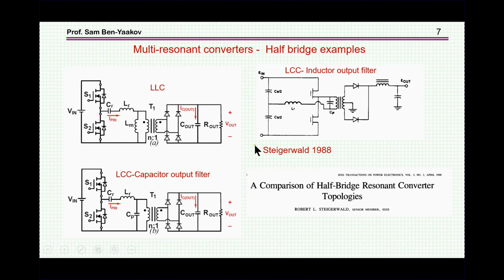Now, there's another way. Here is another parallel resonant converter, because we are connected in parallel to the resonant capacitor. This is the resonant inductor. These are bulk capacitors. They are much, much larger than this thing, and they are therefore not part of the resonant circuit. So in this case, we have a parallel resonant converter.